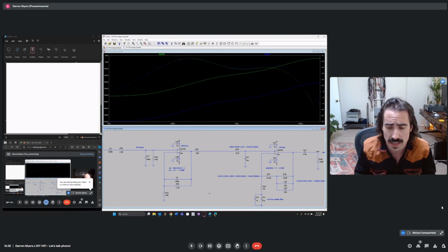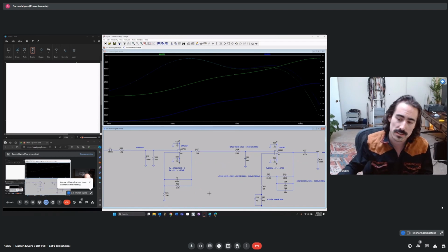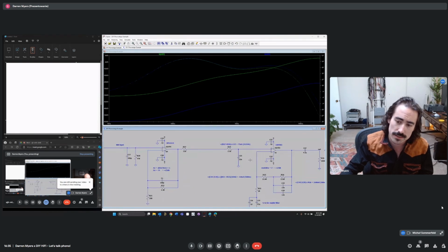And one would ask, why wouldn't we correct the frequency element in this stage? And why are we not applying more gain in this stage? So the answer to those two questions is that in order to start applying the correction, we're going to need to introduce some impedances in order to use attainable values and practical values of capacitors, right?